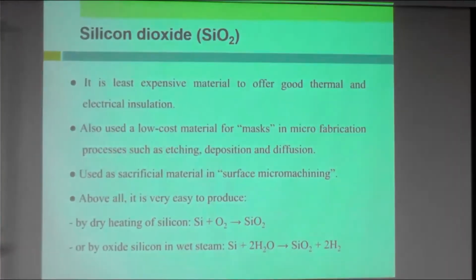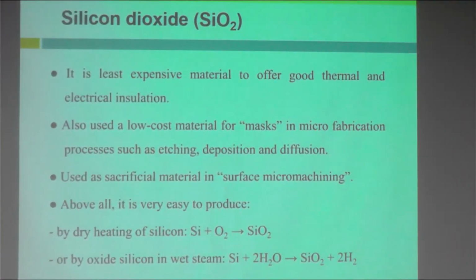different properties. So silicon can be etched by, I can't remember exactly. For example, if silicon can be etched by hydrochloric acid, for example, then silicon dioxide is not. So that's why it says here that it can act as a mask. Mask meaning to protect the silicon from being etched or removed or attacked by certain chemicals. So silicon dioxide can be used as a mask as well.